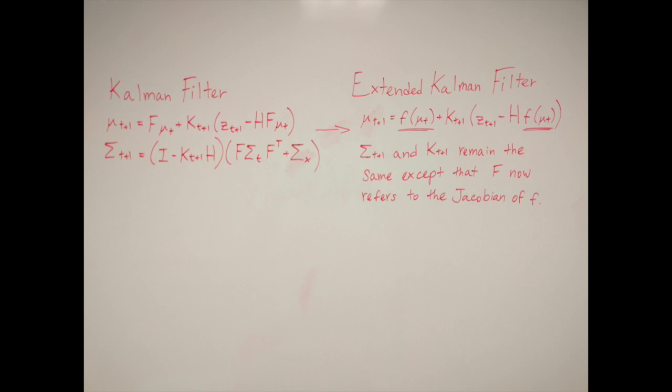However, we found that the Kalman filter was unable to account for the two-wheel drive model of our robot. We therefore turned to the extended Kalman filter, which is built to handle nonlinear transition functions. Moving to the extended Kalman filter requires two changes from the vanilla Kalman filter.